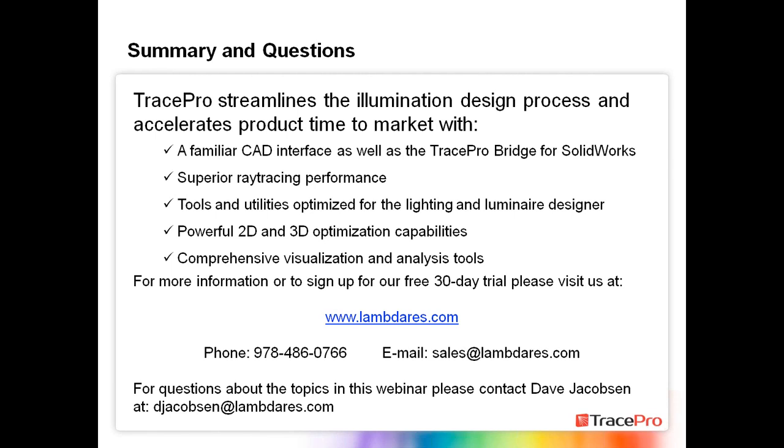As a test, after I optimized the reflector and then optimized the diffuser, I went back and tried to re-optimize the reflector with that diffuser I found. And in this case, it made very little difference. So for a process like this, I tried to do as much with the reflector as possible and then add the diffuser.